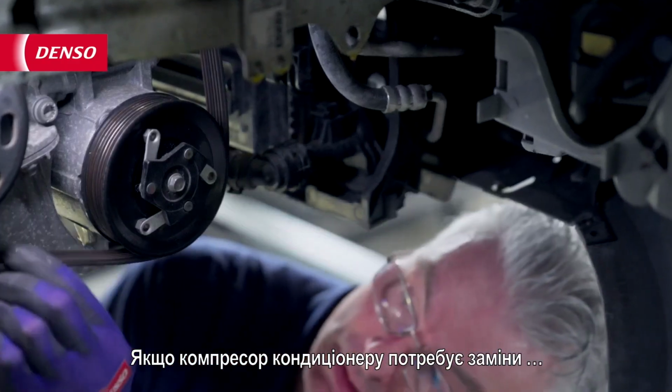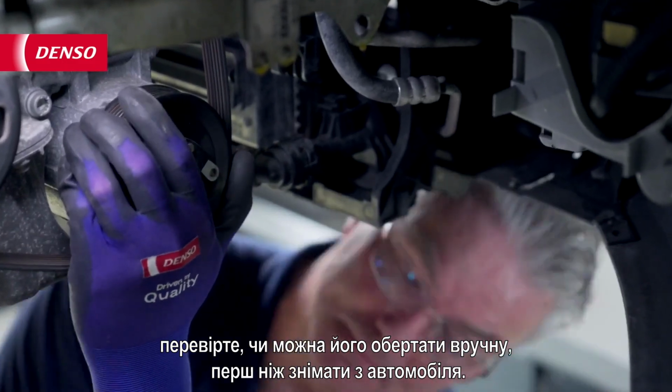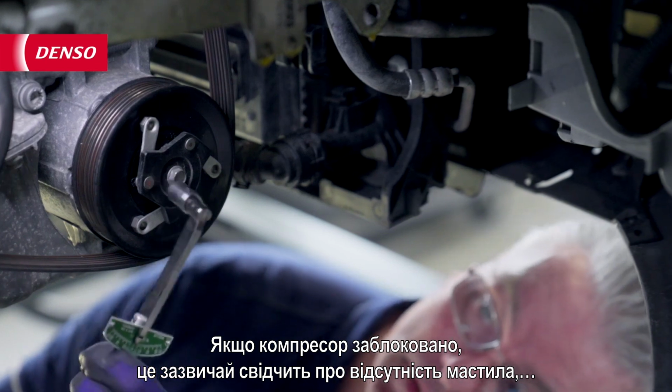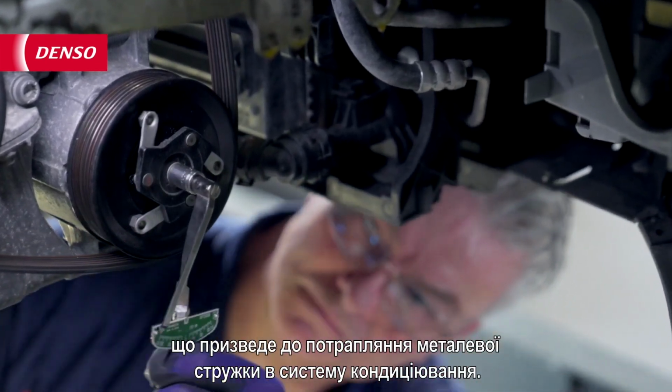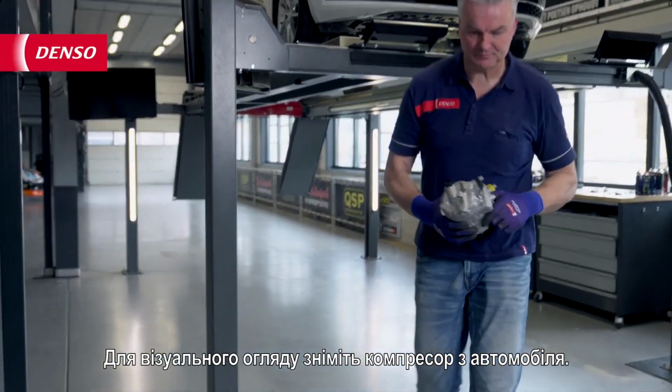When the AC compressor needs replacement, check if it can be rotated by hand before removing it from the car. If the compressor is locked, it usually indicates a lack of lubrication, which will result in metal debris in the AC system. Remove the compressor from the car to perform a visual inspection.